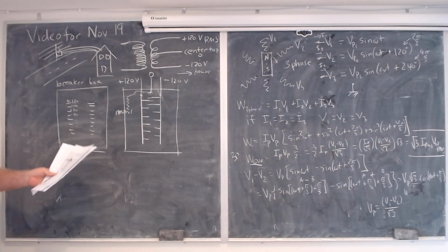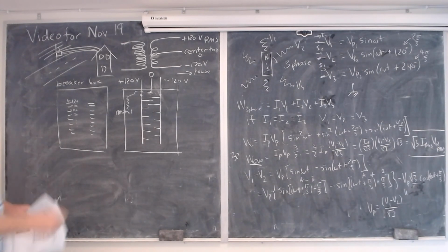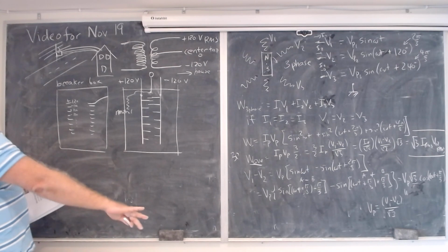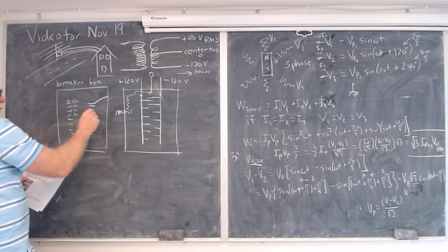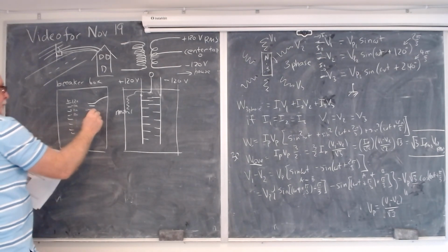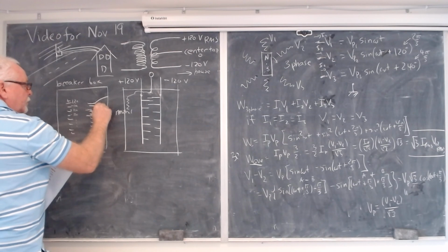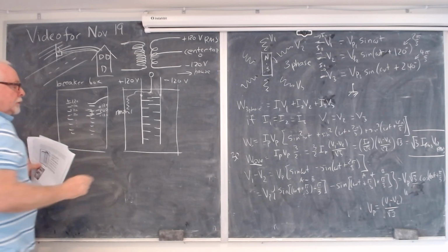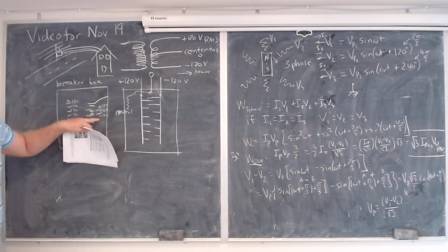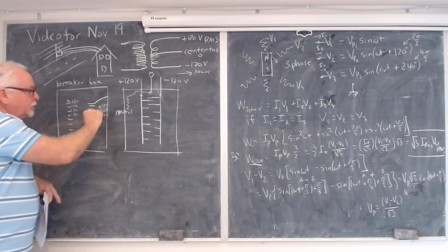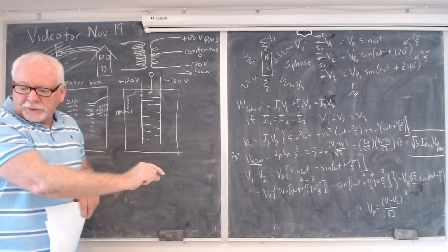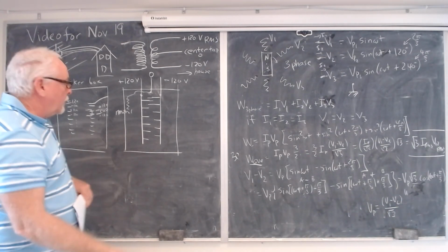And so most of the circuits in your house are just 120. If you look at it, there's a wire in here going off of one of them to a bunch of outlets in your house. But every once in a while, you see 2 of them ganged together. That's because plus 120 and minus 120 is going off to your house, so that's a 240 circuit. For example, your oven would have wires from 2 adjacent breakers going off to it because it has to have a lot of power, supplying 240 volts.